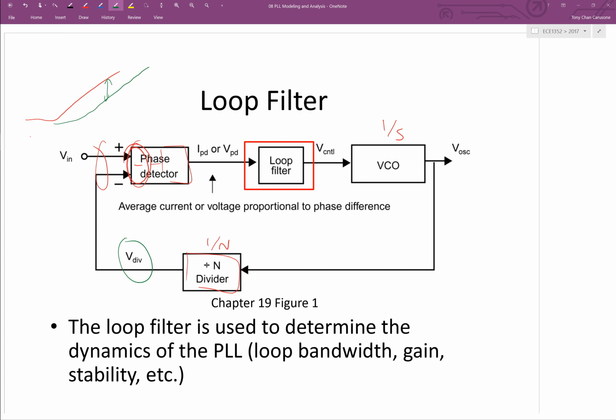So usually you don't think of a type 1 loop as being a phase lock loop. It will phase lock if there's zero frequency error, but how could you ever ensure that? As soon as there's any frequency error, then what you get is something that's frequency locked but not phase locked, right?